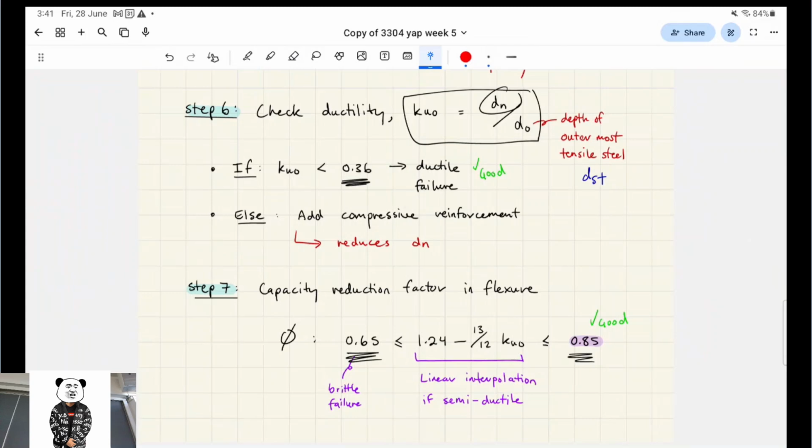So you want the concrete to show signs of cracking first, right? Cracking is kind of expected in concrete, but you'd rather it do that than completely break without any cracking or notice. Concrete to fail before the steel fails? Yes, that's actually right. So the idea is, no, it's the other way around. If the steel yields first, it actually gives it that ductile property.